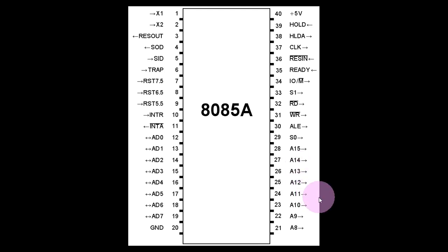No, you can have a multiplexer and connect multiple devices from AD0 to AD15, right? To be able to tell which device is being used, you have this IO/M-bar operation, and if the value of this is 1, we are dealing with an input output device, and if the value is 0, we are dealing with an externally interfaced memory, right?